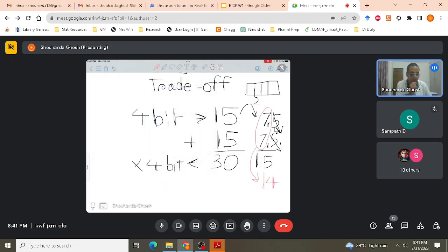Now you see what has happened over here. Now if I want to gain back my original number, I will scale it back by a factor of 2. So what's 14 into 2? That's 28. I will store it as 14 in my 4-bit register, but outside, when I see this 14, I will multiply that by a factor of 2.